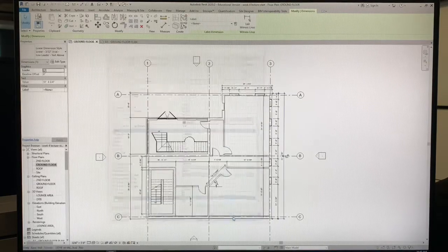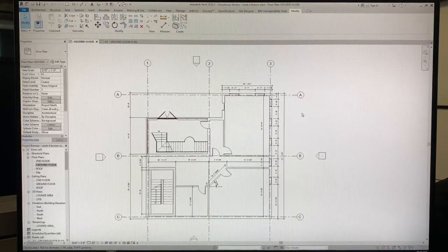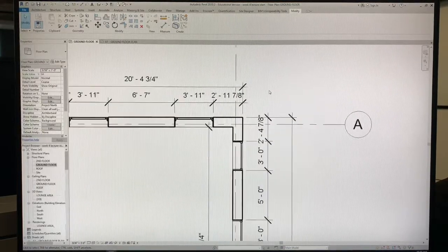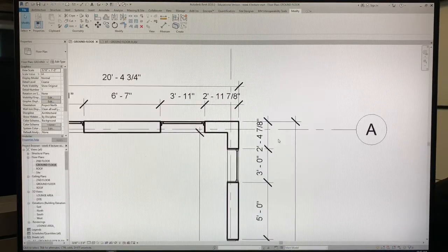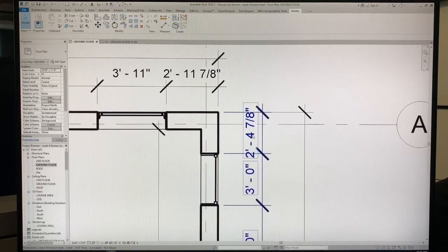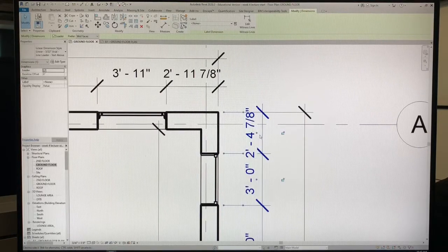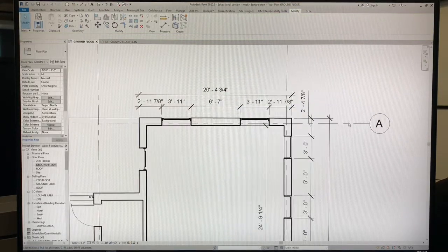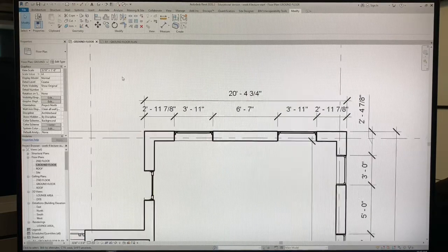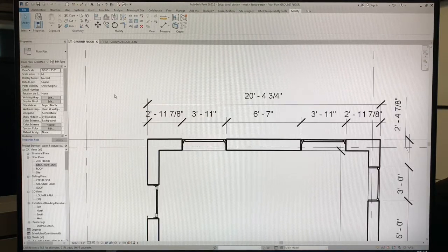That's one way of making it fit. So again, I said I can't make my text size smaller than that. So what I'm going to do is pull that dimension out. Select that dimension. You'll see a little grip feature appear on that. And then I can pull my dimension out, and you can see it comes with a leader line, so I can pull that dimension out like that, so as to not merge into my extension lines.